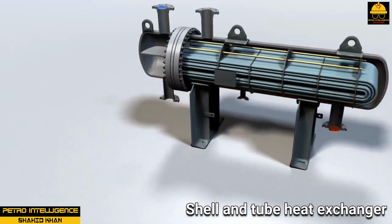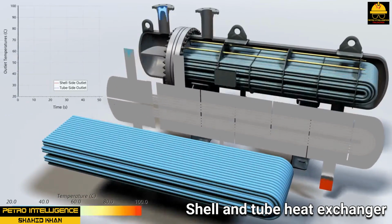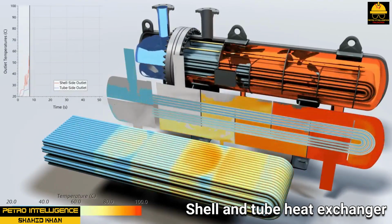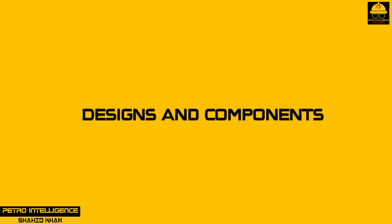Fluid flow into and out of the heat exchanger is designed for specific liquid-vapor services. Liquids move from the bottom of the device to the top to remove or reduce trapped vapor in the system. Gases move from top to bottom to remove trapped or accumulated liquids. This standard applies to both tube-side and shell-side flow.